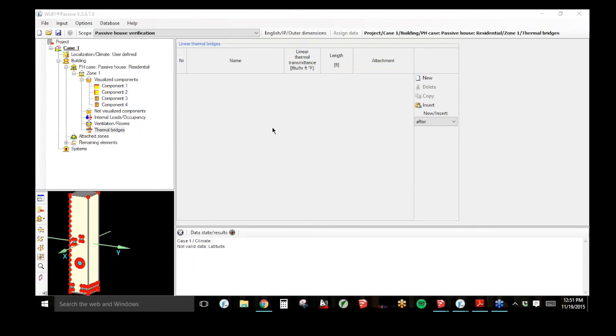When drawing windows in SketchUp, how accurate do you need to be with size and placement of windows on the SketchUp model? Size is very important. Placement is not that important. So size, you do need to use the actual window size because it greatly affects transmission losses through the frame and the glass, and also solar gains. Placement, it really only knows the orientation. There's no spatial resolution, so it doesn't know when a window is right next to another window. So not quite as important. If you're getting into zones and zoning off a room with a big window, looking for localized overheating, placement's important. Try to get it as close as possible, but it's not absolutely critical.